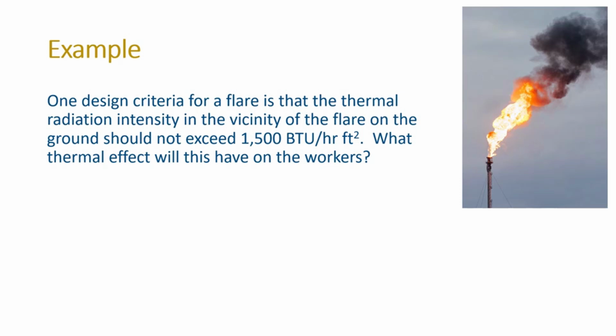And one design criterion for a flare is that the thermal radiation intensity in the vicinity of the flare on the ground, so again, speaking of the impact on workers, should not exceed 1,500 BTU per hour foot squared. The question is, what thermal effect would this have on the workers?